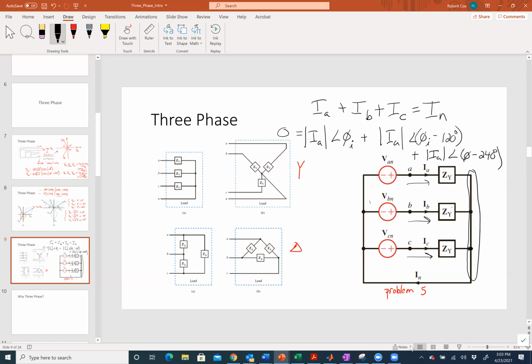So Zach, you talked about that in terms of burning up. What's happening to cause heating in a wire? Resistance, right? There's resistance in the wire, so there's I squared R heating that's happening. The fatter I make the wire, what's happening to the resistance? Yeah, the resistance is going down as the wire gets fatter. So tell me about the gauge of wire I need for IA versus IN.